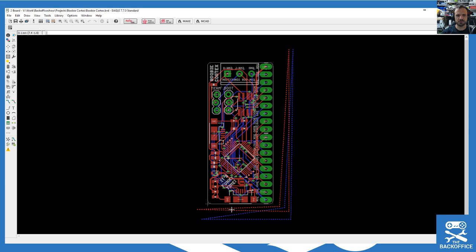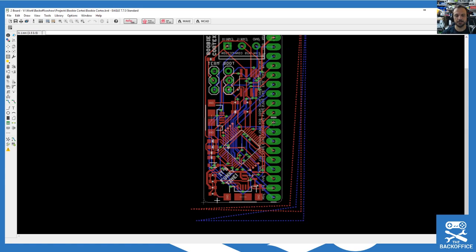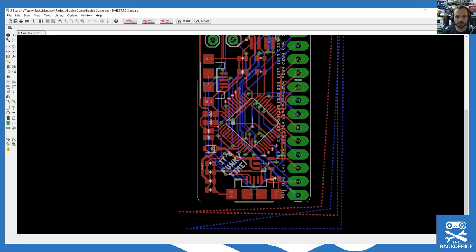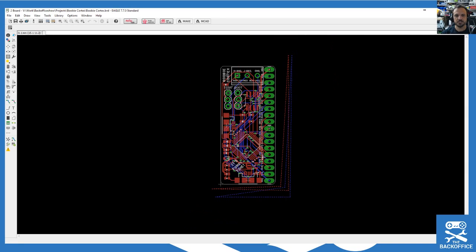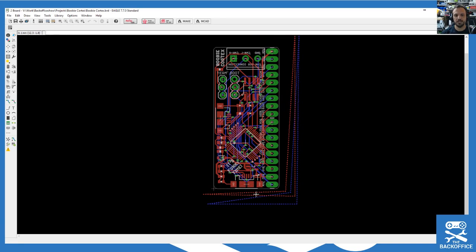So I'd just like to describe some of the features of the board before I show you what I'm actually up to. It's dual-footed for USB. So the reason it's got a USB on the bottom here, in the vertical plane, as well as one on the side, is that because it's got a CAN bus header on one end and then the USB on the other, you could just use it as a dongle with some heat shrink. So that's kind of an inline mode.